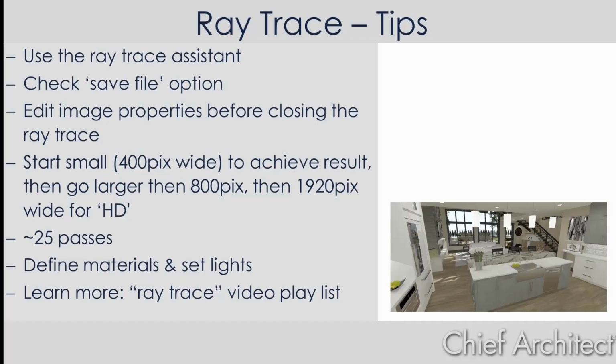Okay. Little tip, if you do ray trace rendering, make sure you use the assistant when it comes up and start super small because they can take a while. I usually start with 400 pixels wide, and once it starts to look good, then I'll increase it to 800 pixels. And when that looks good, I'll go to dinner or go to bed and crank it up to about 1920. Again, I like to use the high definition.